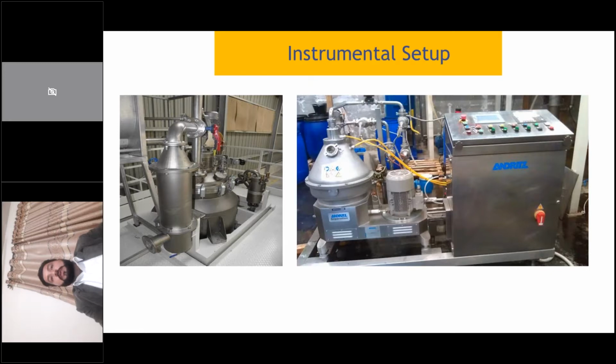So we start with the raw material, and we can obtain the nanocellulose in any form, whether we produce it in a dry powder form or in the form of a suspension. Then it is subjected to morphological analysis and XRD analysis to check whether the size of the fibril is in the nano range or not.